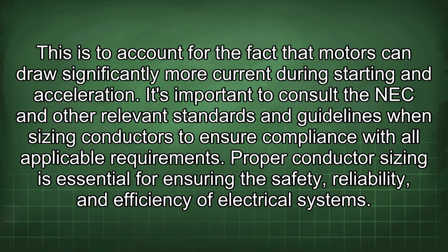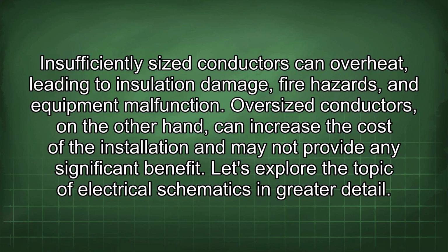It's important to consult the NEC and other relevant standards and guidelines when sizing conductors to ensure compliance with all applicable requirements. Proper conductor sizing is essential for ensuring the safety, reliability, and efficiency of electrical systems. Insufficiently sized conductors can overheat, leading to insulation damage, fire hazards, and equipment malfunction. Oversized conductors, on the other hand, can increase the cost of the installation and may not provide any significant benefit.